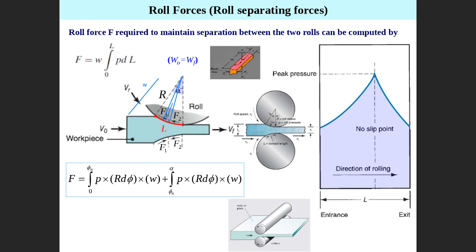This is the small pressure applied here. Then you can see that the pressure multiplied by the area, which is dl multiplied by w. This is the small area of the element. We take an element here. This is a small area, so small area equals dl multiplied by w. Then the pressure multiplied by w is constant, no change, multiplied by dl, and then we do integration from 0 to L to cover all the areas, then you get the force.